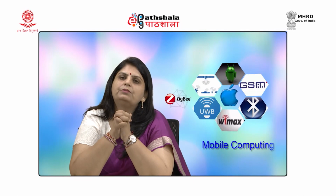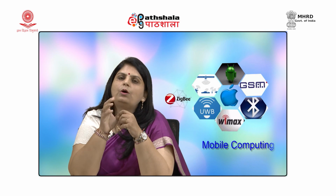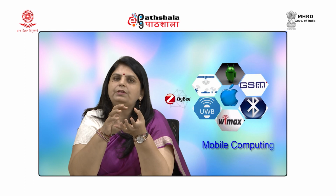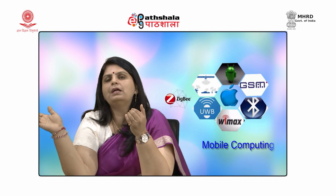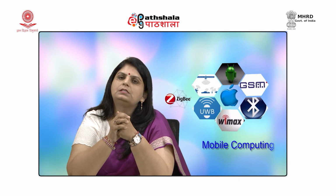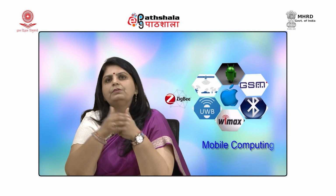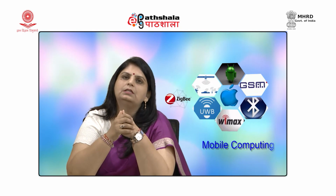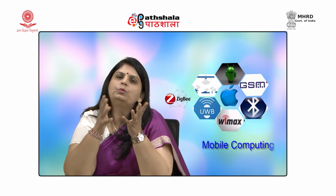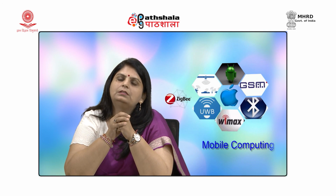Then we learnt about the phenomena reflection, diffraction and scattering, and the objects which offer these types of phenomena. We learned that when reflection takes place, the signal changes its path, it might be absorbed by the object, and it reaches the receiver following a different path with different intensity. Diffraction causes the waves to bend around the obstacle and reach the other side. The scattering breaks the signal into weaker components. The higher the frequency of the wave, the smaller the objects required to scatter the signal.